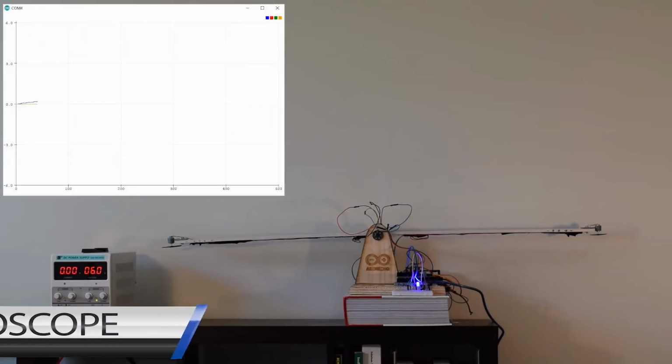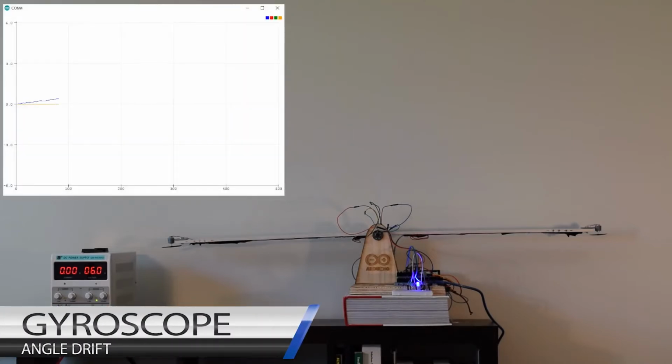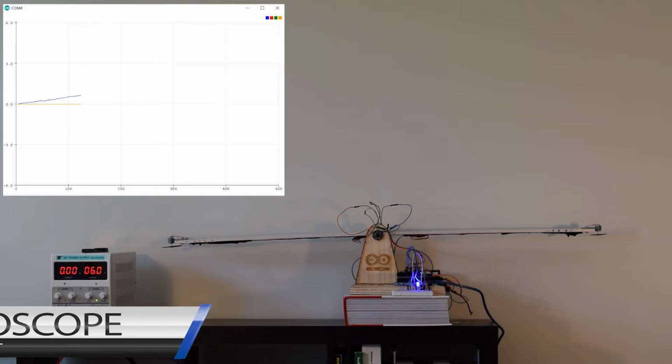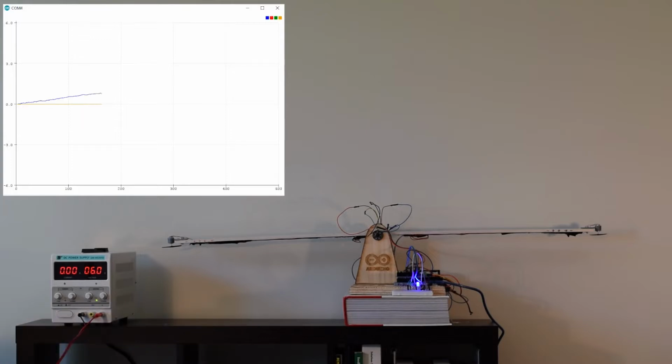One of the biggest challenges for me in this project was managing the angle drift from the gyroscope. To manage this issue, I regularly monitored the gyro angle drift using a serial plotter. The y-axis of the graph shows the angle and the x-axis represents each time a print command is executed, which is a function of time. The set point is shown in orange and the angle recorded by the gyro is blue.